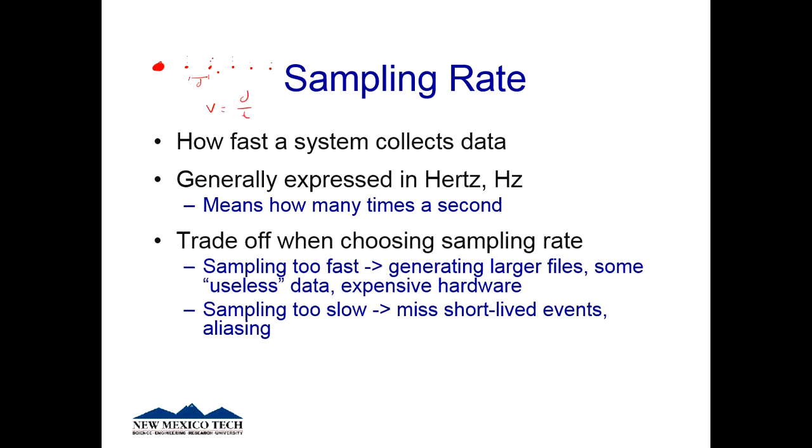So why am I saying all this? Well, in order to capture that shock wave, which may be moving, something like a C4 could be moving 20,000 feet per second, you've got to sample really quick to make sure you got it. Your sensor has to say: give me a pressure measurement, give me a pressure measurement, give me a pressure measurement.